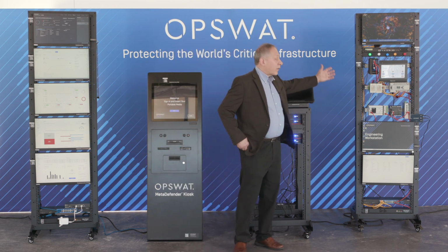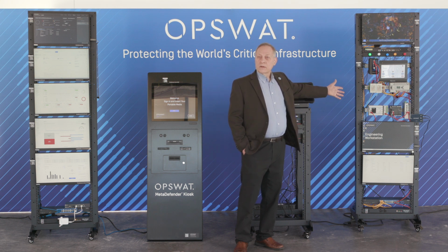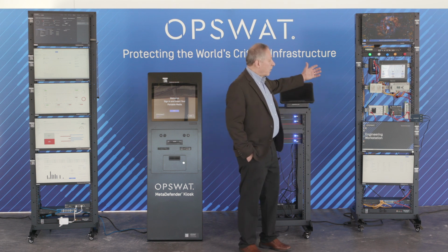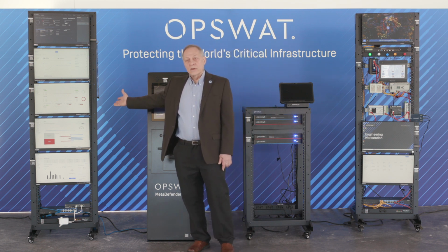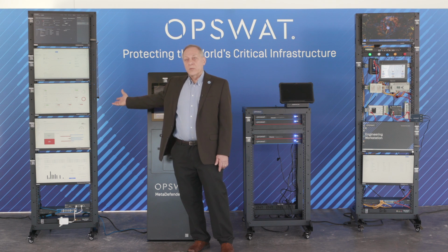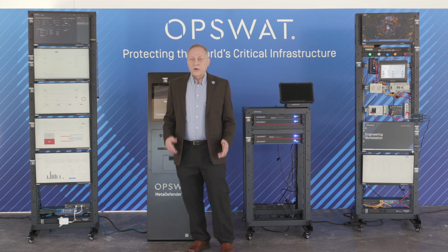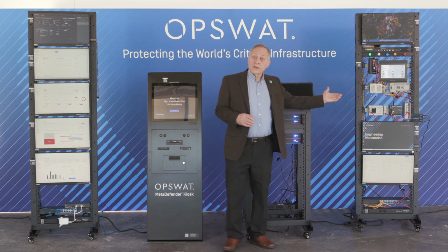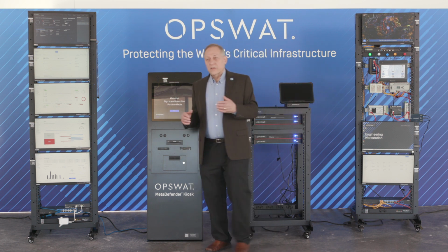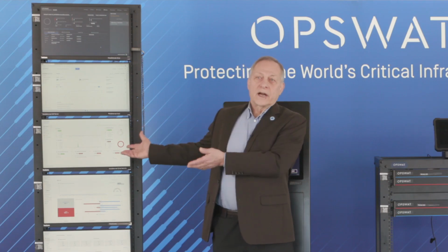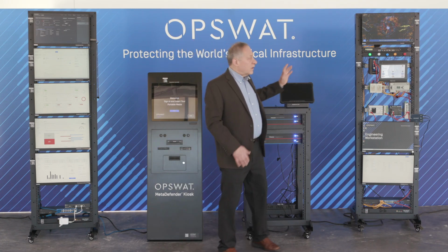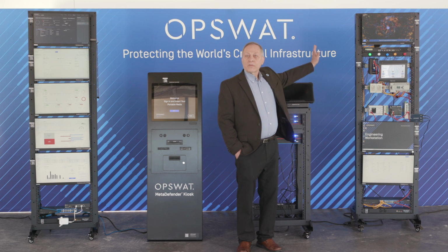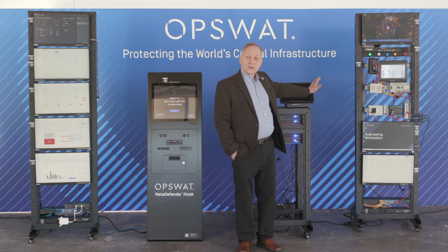It can. We don't have one running here, but if we had a historian, such as an OSIsoft PI historian or an AspenTech IP21 historian, it'll replicate the historical data across the perimeter to an instance of the historian in the IT domain or up in the cloud for that matter. Thereby, if there's an issue in the OT environment, you can take a look at the historical data that's been replicated into the IT domain and determine what caused the issue. Further along, that actually concludes the network protection platforms that we have for the industrial control space.